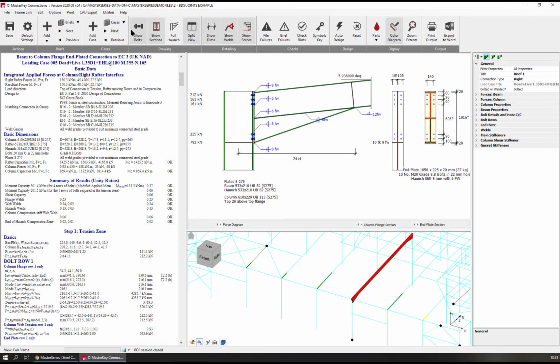And that's the beauty about linked design into the frame analysis. Because if you're dealing with a portal frame or any rigid sort of frame and you're dealing with sway stability, eaves moving that way is going to relax the joint. Eaves moving this way is going to harden up the joint, so the two moments will be ever so slightly different. So the different directions will give you ever so slightly different values.